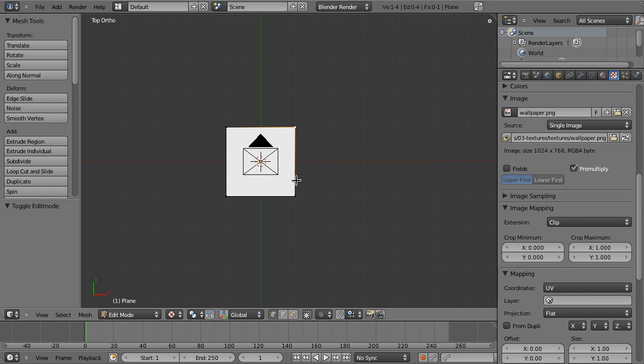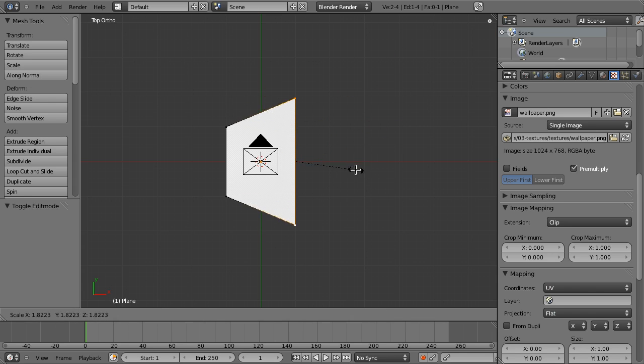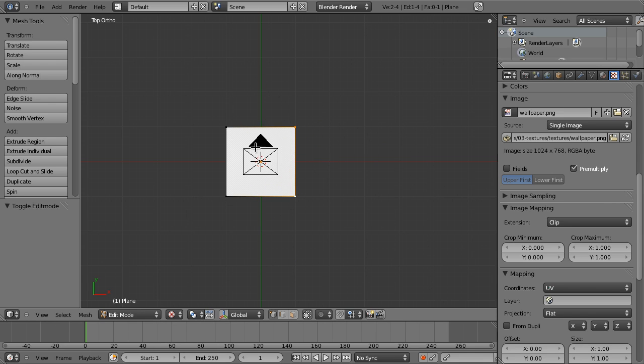So the surface, the plane that we have, is actually a face, the surface between 3 or 4 vertices, which are these little points in space, and we can actually assign the mapping as well as edit. Like I could use the same sort of transformation, G for movement, S for scaling or rotation. You can do that, but you're working on the mesh itself, not on the object.